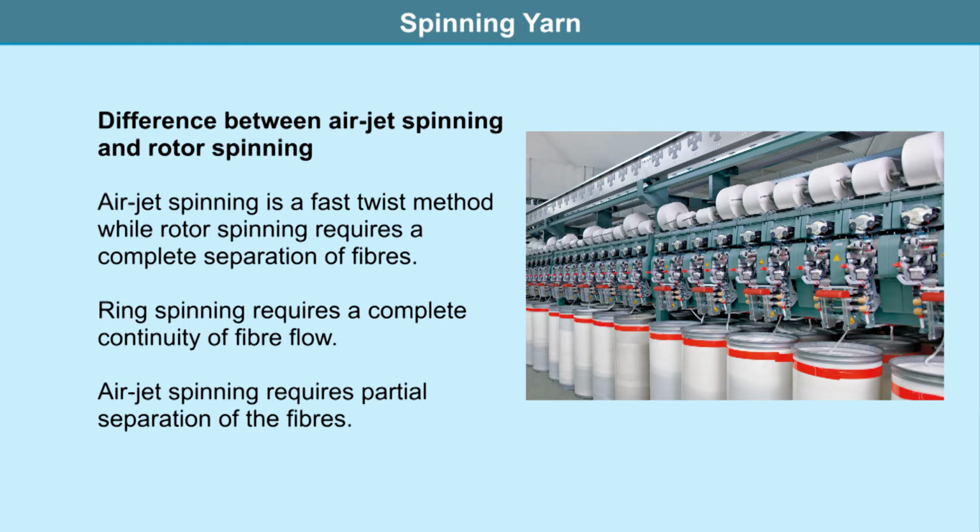Well, a splicer is one thing which joins the broken ends of the yarn and it avoids putting the knot, and the splicer works on the suction principle, and the very fact that the knots are not put will be advantageous because the knots get caught in the reed of the weaving loom, and then it may result in a break. So splicers are found to be beneficial, and most of these cone winders today are equipped with this facility of putting these splicers in the yarn whenever there is a breakage.